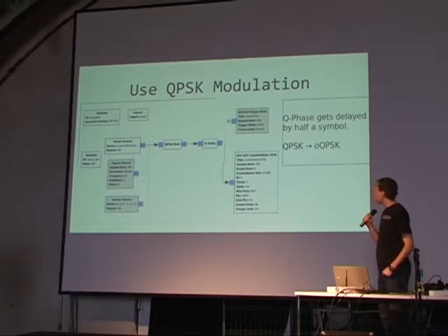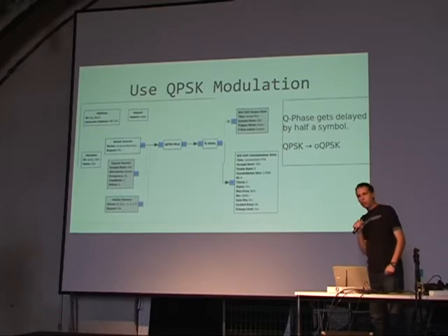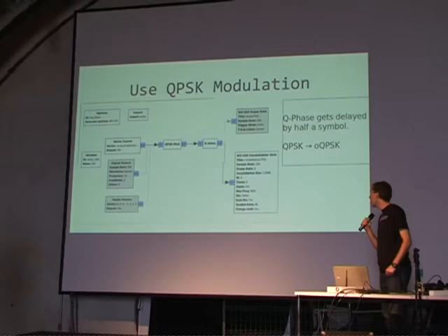You can either pass this afterwards to a scope sink, which practically shows you a graphical scope, or you can pass this to a constellation to look that your modulation works properly. You can have different sources to debug your modulator, so if you see that it practically represents something you don't want to have, you can therefore find your bugs visually.